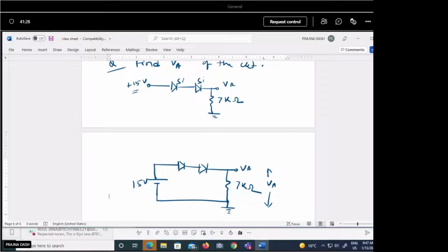If you reverse the polarity, black on the positive side and red on the negative side, then that same voltage will appear as minus some volt. So we will get negative polarity. So to get a proper voltage, it is the practice, as per the color indication, that red color is kept at the positive terminal, higher potential, and black at lower potential. So whenever voltage is given at a particular point and the other point is not given, it means that voltage needs to be measured with respect to ground.